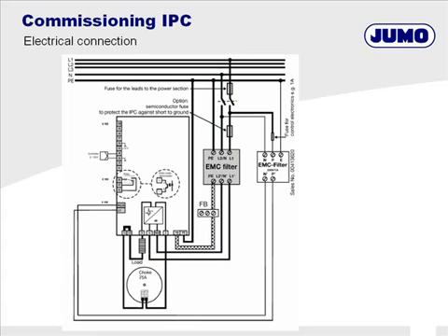The voltage for the load circuit has to be connected. Due to the connection of load and choke, they are connected in series. The shown connection of the controller applies to a signal of 0 to 10 volt. This usually corresponds to a signal of 0 to 100%.